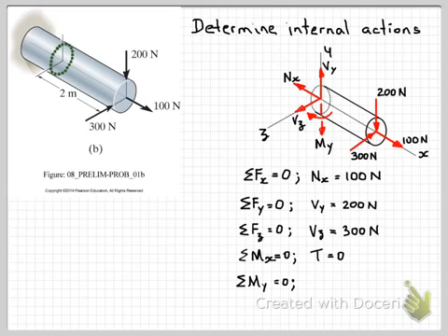So for equilibrium, we need to resist that moment around this way, so our internal reaction moment is shown in this direction. Note that when I draw the vector moment, I show it actually as a vector. So this arrow here is not a force, that's just the vector direction of this moment that we've applied.